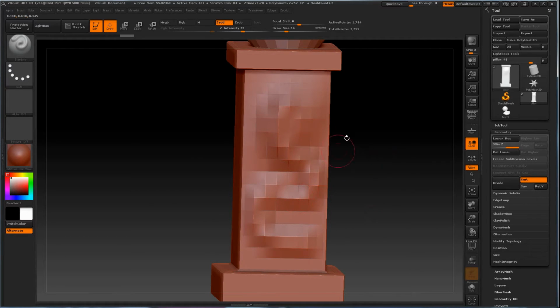However, if I wanted to get a smaller resolution line, let's say I go to the draw size and I go something small like 9, and I want to start drawing some super detail, it's not really going to do much because there's not enough polygons to create deformation. So I can push the divisions a little higher. So let's click divide again. Now we're at division level 3. So now when I start drawing, I can start to get a little more precise.